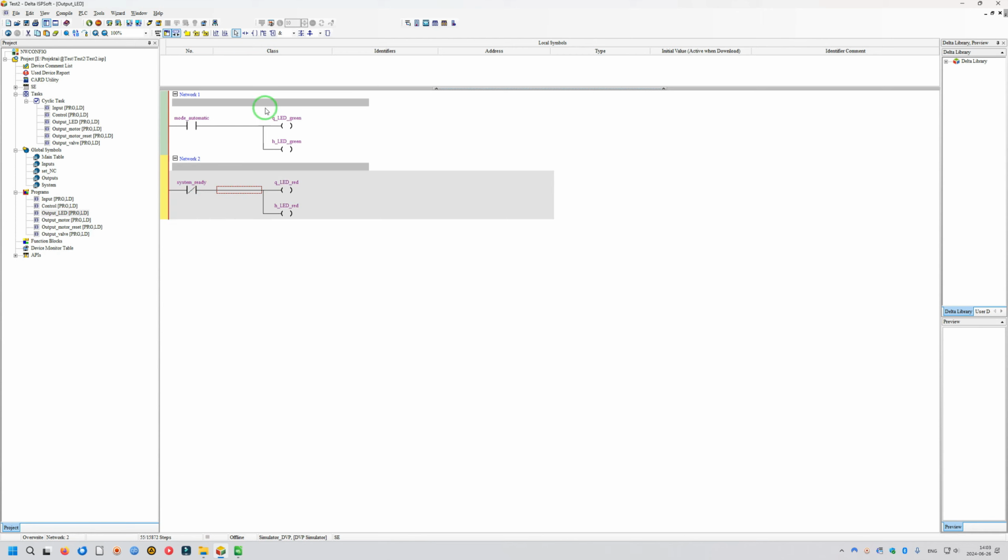But what I like to do is to have two states for the red LED, I always said. So one state when I don't have system ready bit, what I do, I am blinking it. So let's add blinking. Do not use high frequency, especially if you have relay output here, not a transistor output. So be careful with this. Do not use high frequency blinking on relay outputs.